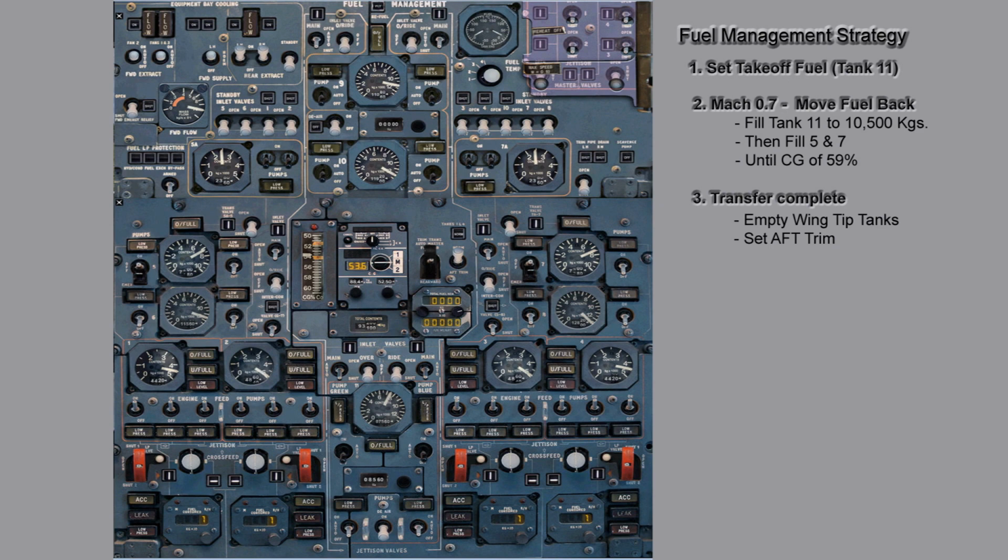After we've initiated the emptying of the wingtip tanks, we're going to balance fuel left to right, port to starboard, or whatever, and we have to move fuel across the ship to balance the fuel and relieve pressure on the elevons.